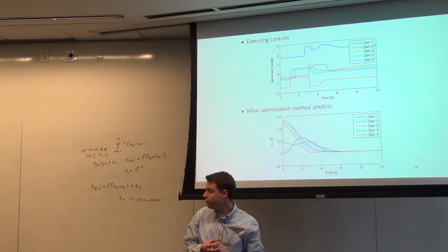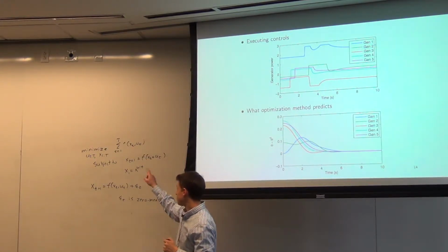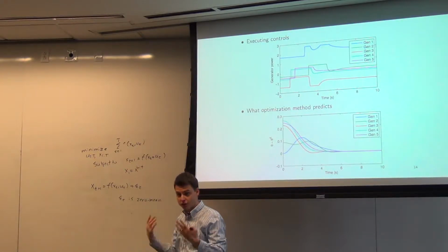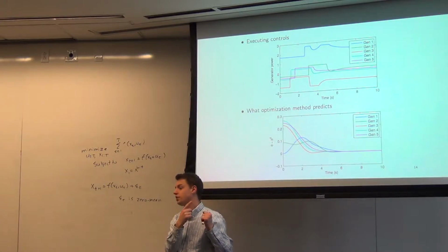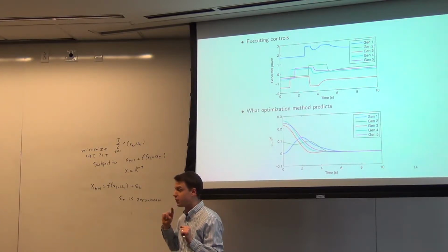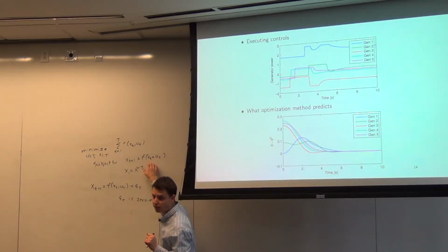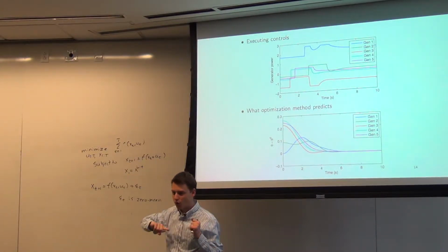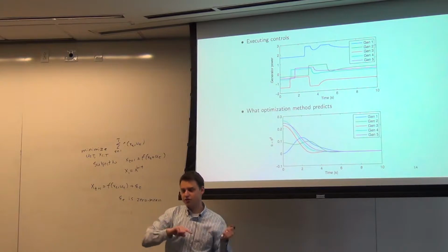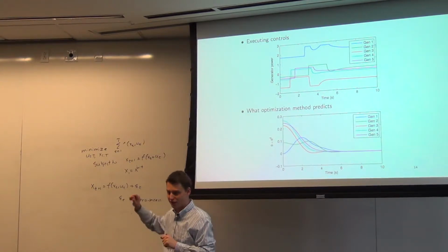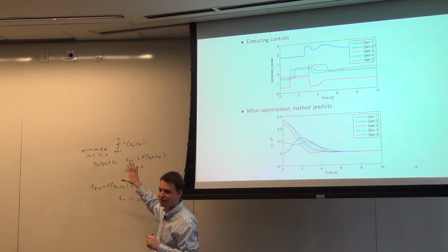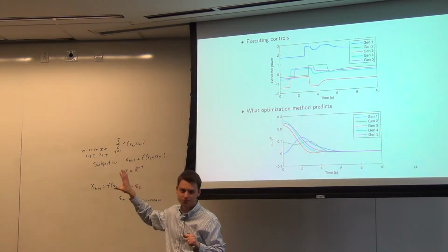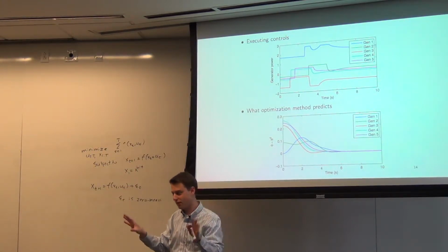And you'll remember, one of the advantages of this optimization formulation is you could also do things like put convex bounds on the constraints themselves. So in our example here, the system was linear. So actually, we sort of had the nice effects here. Though even when it is all linear, even though LQR works, once you add constraints, you still don't have optimality. So actually, the optimization formulation still is not the optimal stochastic controller. I won't prove that, but it just is something that holds.